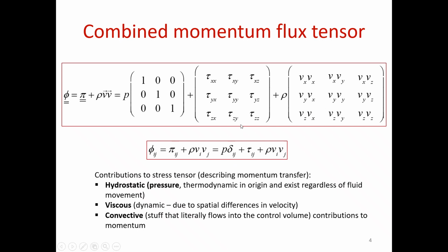I haven't told you anything about the nature of the fluid yet. So in this particular formulation, this is true for Newtonian and non-Newtonian. It's how you describe this tau ij that differentiates which fluid I'm talking about. And for Newtonian fluid, that's where our relationship between shear stresses and the velocity gradient is linear.